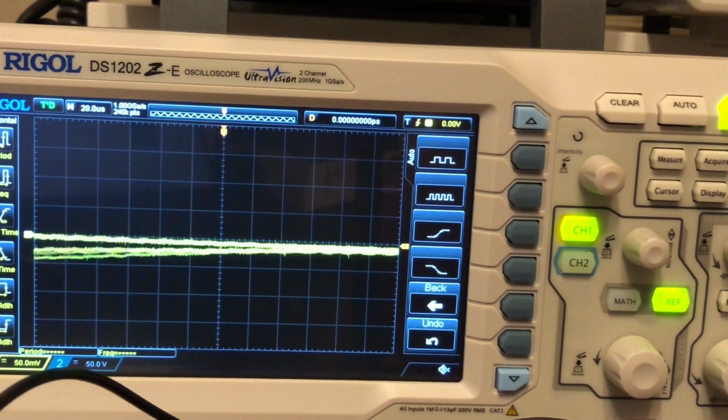Waveform auto setting function requires that the frequency assigned is no lower than 41 Hz. The duty cycle should be greater than 1% and the amplitude must be at least 20 millivolts peak to peak for square. Otherwise, the waveform auto setting may be invalid and the quick parameter measurement function displayed in the menu will also be unavailable.